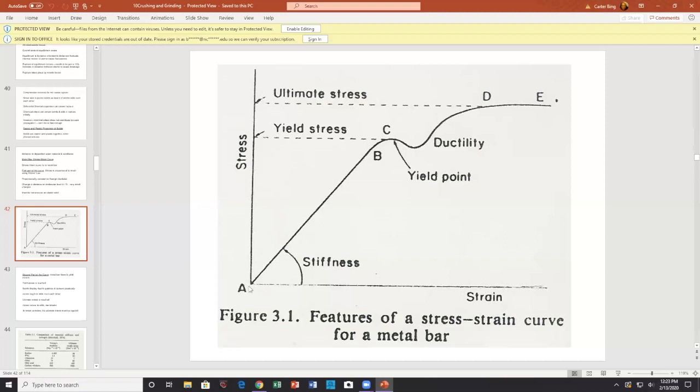I can cause it to significantly increase in stiffness, which makes the ultimate stress more reachable in operations. And I would also, in such circumstances, check to see if the ultimate stress changed as a function of temperature. So the slope of this line is a function of temperature. Also the ultimate stress is a function of temperature. So away we go. We got all kinds of little variations we can run on this diagram. And it would be interesting to know if you have this diagram for your material.